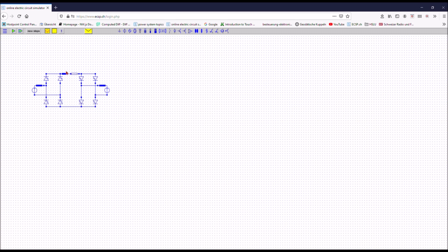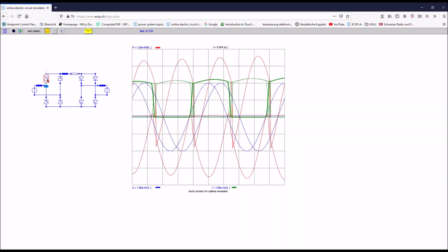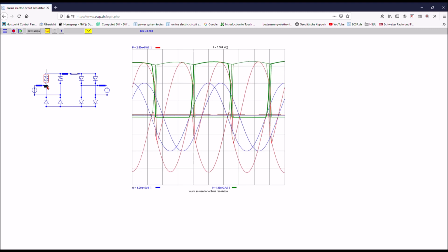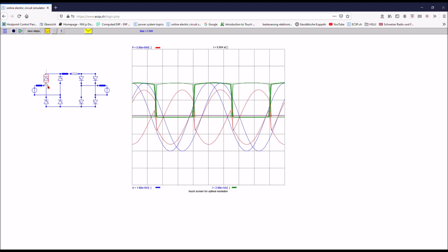Here you have the line with something like 2 millihenries, and then you have a line resistance, which is a couple of ohms. And you control the power flow by controlling the voltages at both ends, and you do that by means of the thyristors. And you can now control the thyristors altogether. So you control the thyristor on the sending end. You have to be a little bit careful, otherwise you destroy the commutation.